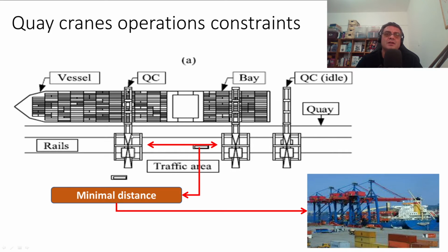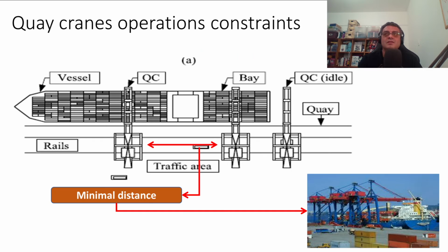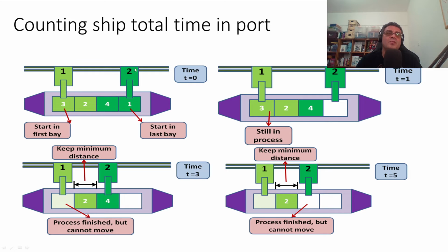Also, these rail-mounted equipments cannot overlap each other, so you have specific dynamics, which you should use if you want to account in detail for how much time is needed for quay crane operations. In track 5, we developed the rules to operate two quay cranes, and we can generalize this procedure to as many quay cranes as needed. Most importantly, this is a simple function that gives us a correct expectation of how much time the joint operation of these two quay cranes will take.